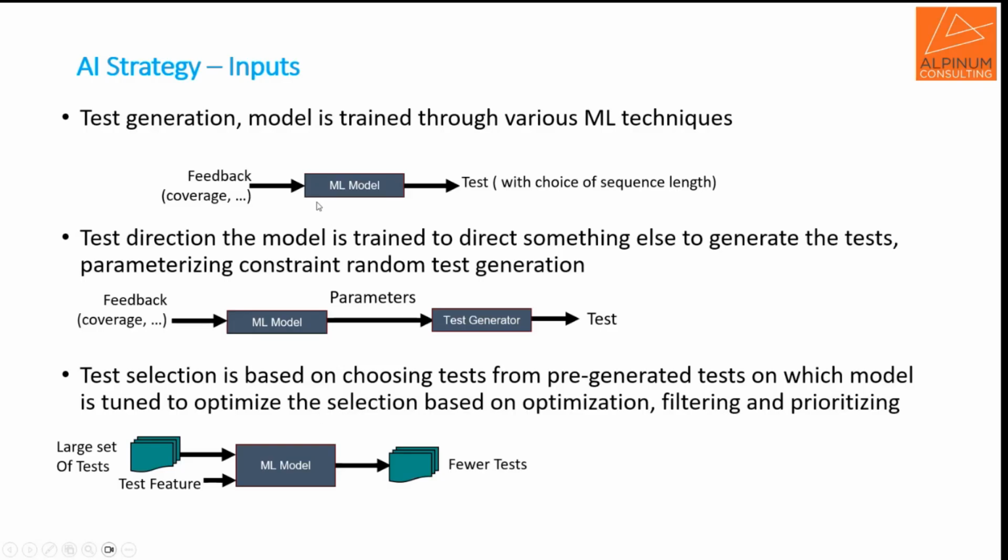In these three flow diagrams, you can see that based on the coverage feedback, the ML model that we employed is going to set how the test generation is affected and how the tests will be generated, and how we want the test to generate a particular stimulus scenario based on what we want to cover and hit. It's also controlled by, for example, the constrained random verification environment, but the model is going to guide the generation of the test.